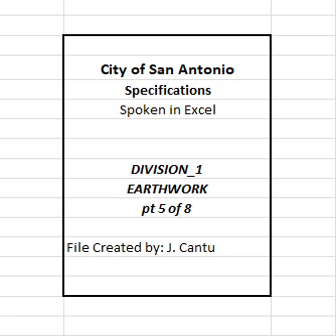B. Rock embankments. Rock embankment is mainly composed of rock. Construct rock embankments in successive layers for the full width of the roadway cross-section with a depth of 18 inches or less. Increase the layer depth for large rock sizes as approved. Do not exceed a depth of 2½ feet in any case. Fill voids created by the large stone matrix with smaller stones during the placement and filling operations. Ensure the depth of the embankment layer is greater than the maximum dimension of any rock. Do not place rock greater than 2 feet in its maximum dimension, unless otherwise approved.